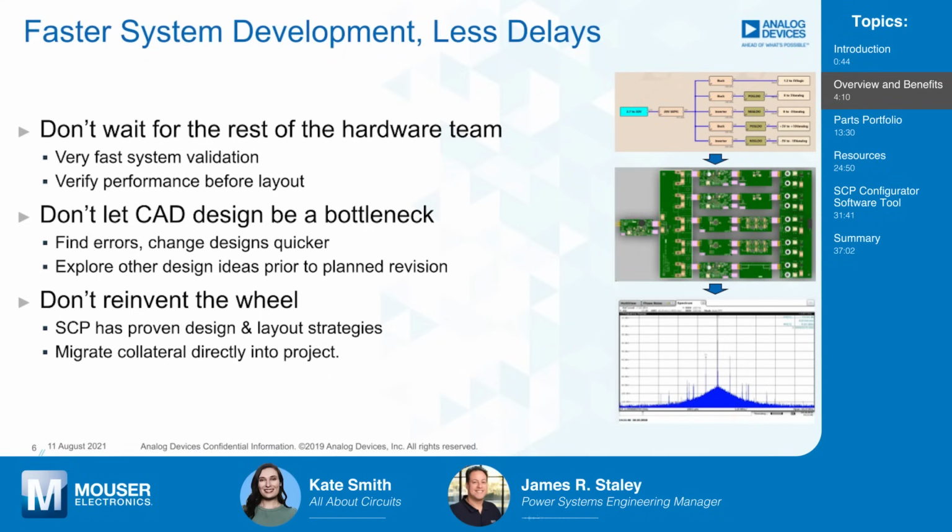And with switching regulators, there's a lot of kind of voodoo that goes into getting the layout just right. It often takes years of switcher-specific knowledge, intuition and expertise to get switching layouts just right so that they're not either oscillating or radiating noise all over the place. And if you stick with the collateral that's available for all of these boards, you won't get into any problems because we've already given you the best layout possible for that part. Right. That makes a lot of sense.